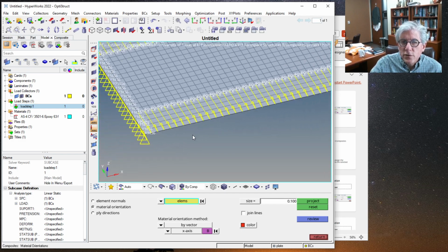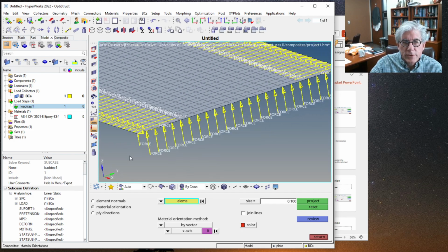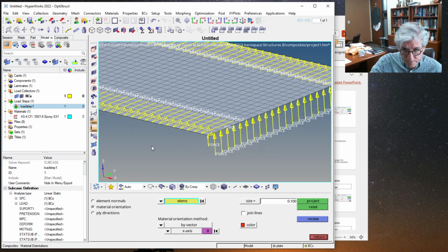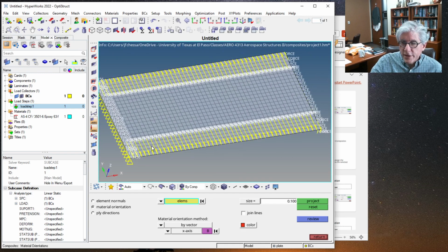So you'll get uniform forces on the uniform elements, and then like half of that on the hanging elements, right? Like you see this force here is half of this because this only has half of an element support, whereas this one's supported under the full element, right? But we've talked about that before, and everything's the same. We created the mesh as shell elements, again, as we've done all before.